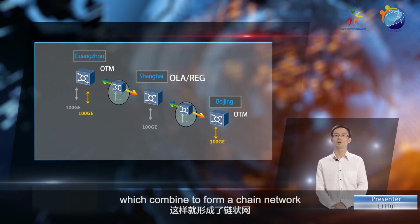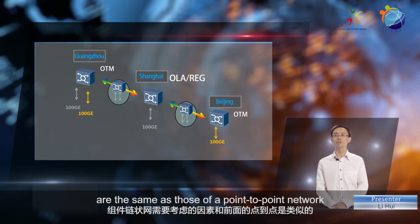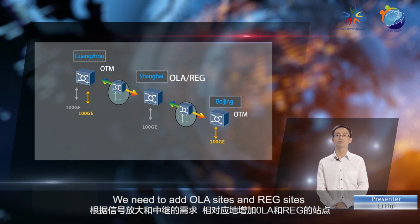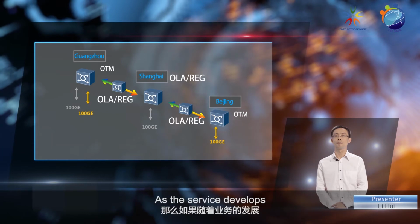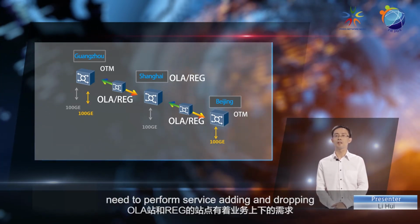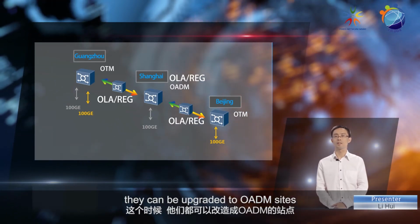form a chain network. Factors which need to be considered in a chain network are the same as those of a point-to-point network. We need to add OLA sites and REG sites according to signal amplifying and regeneration requirements. As the service develops, if the OLA sites and REG sites need to perform service adding and dropping, they can be upgraded to WDM sites.